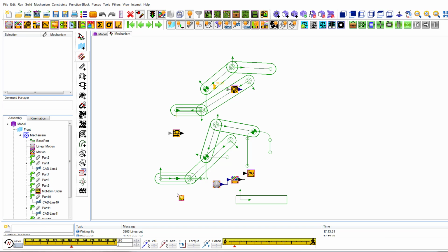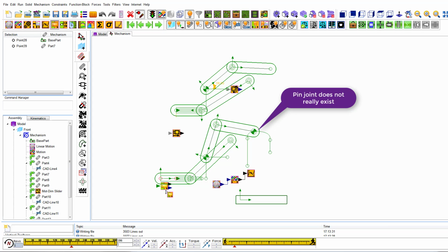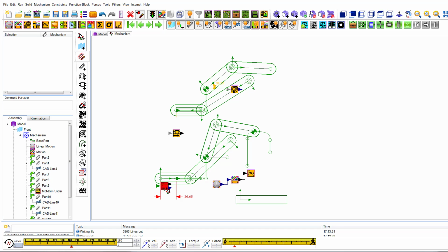This can't be used for calculating forces because it has a fictitious pin joint attaching the second link to the path. This will give the wrong answer because forces will act through this non-existent joint. So we must construct a geometrically identical robot but with different dyads. I will do this very quickly just to show what's involved.